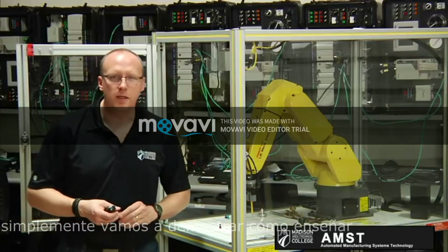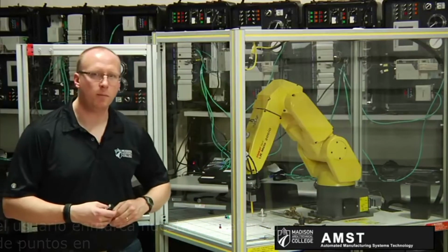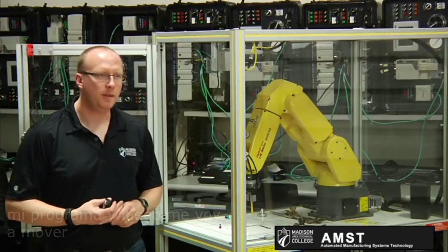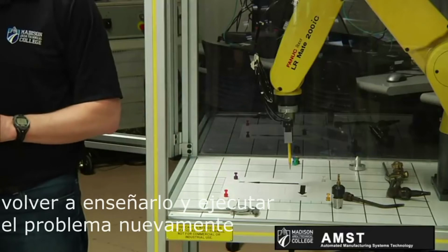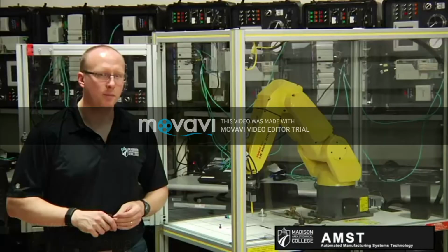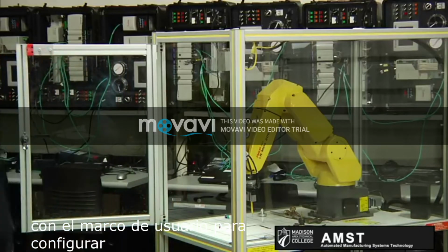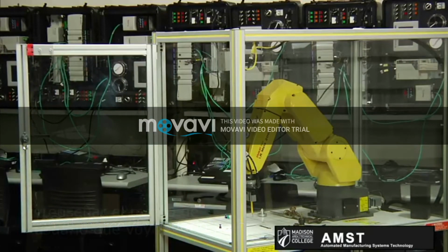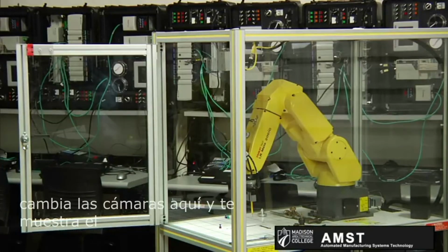So I'm just simply going to demonstrate how to teach the user frame, teach 4 points in my program, and then I'm going to move this user frame onto a different plane, reteach it, and execute the program again, and you will see how that program stays with the user frame. In order to set up and teach the user frame, I'm going to switch cameras here and show you the teach pendant.